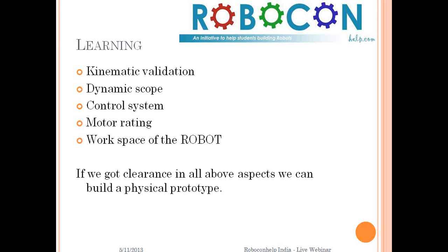Then you can check on the motor ratings. We can check if at a certain motor location we are getting that much torque, and whether my motor is capable of generating that much torque. If your motor is capable of that, or you may choose a certain motor, you can check on catalogs, and you can decide on one good motor for that. Then you will say yes.